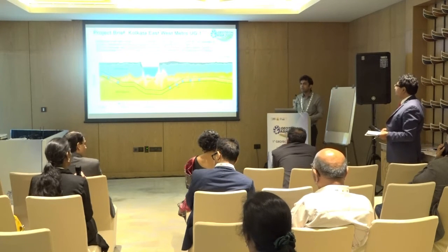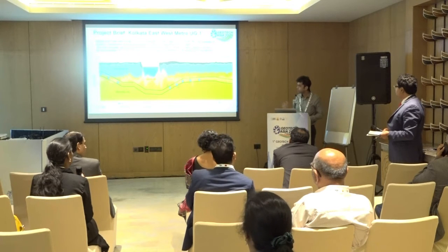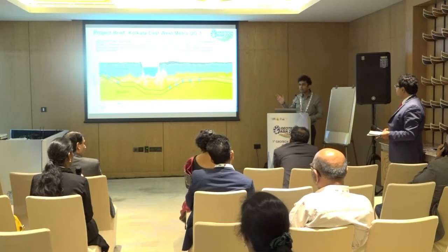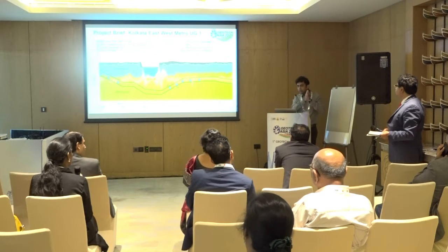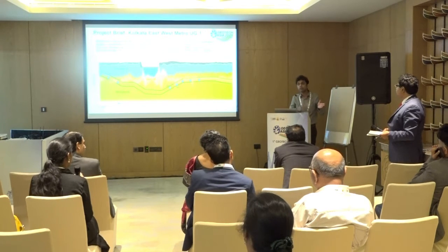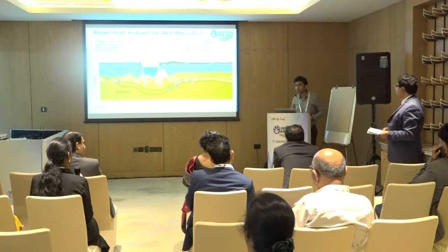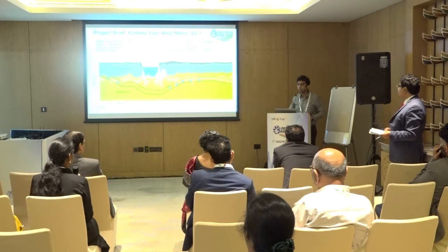I understand, but there has been some study, in the paper that I had cited, whereby they had correlated the UCS values obtained using different tests with the UCS values obtained using the pocket penetrometer. They produced a very good R-square value of somewhere over 0.9. So that basically validated that the use of pocket penetrometers justified the comparison over here in this context.